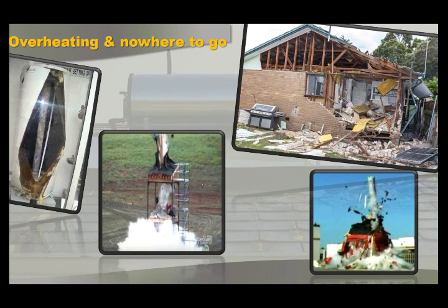Now, in a split system where you've got the tank below the collector, the same principle applies. It's this thermosiphon action that causes the reverse to happen, from the heat from the tank to be dispelled and radiated away in the panels. So it effectively is the same thermosiphonic action. So the point I'm trying to make is thermosiphon will affect every single solar installation. It just affects it. It is a phenomenon that will occur. Nature insists that it does occur, and science insists that it must occur.